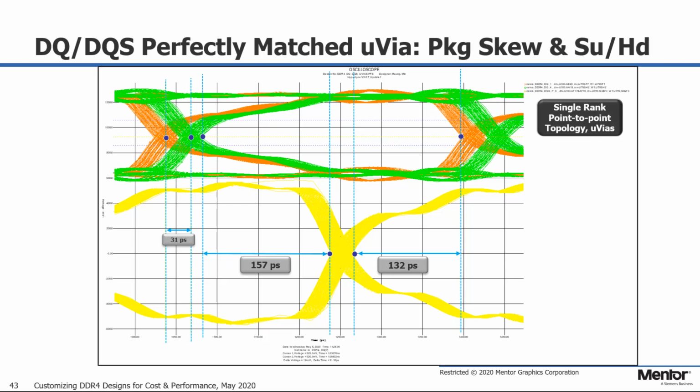So you will need to simulate to understand how to derive the length requirements between DQ and DQS for your particular byte lane, especially if your controller doesn't perform per bit calibration. If you're routing another byte lane on another layer, you will want to investigate that case as well.